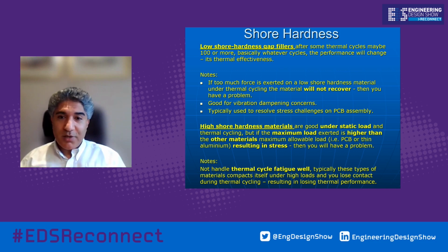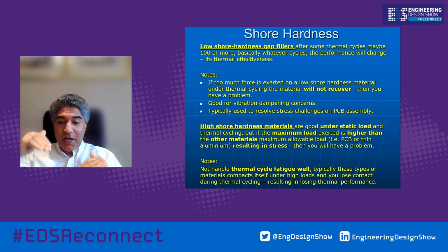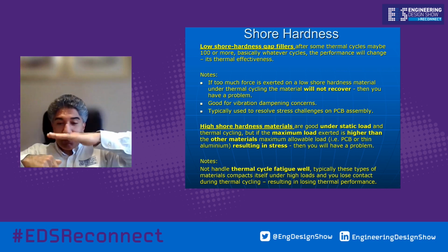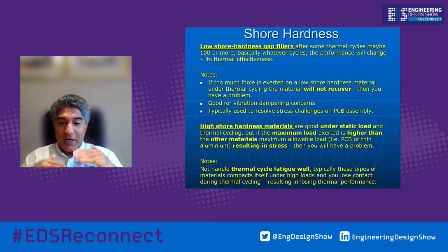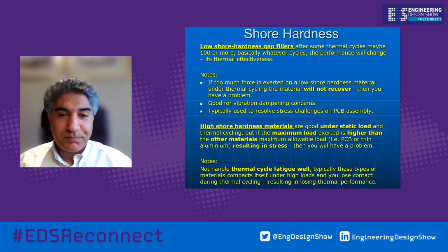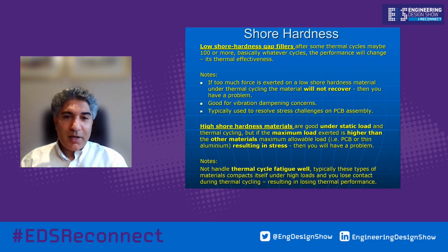High shore hardness material on static applications, yes, it's going to keep its shape. However, under vibration conditions, it'll go through the material and onto the solder joints or rattle the circuit board. So if you've got vibration movement, please try to avoid high shore hardness material. But please note that high shore hardness material is not going to be able to handle the thermal cycling. It will have thermal cycling fatigue in those kinds of materials.